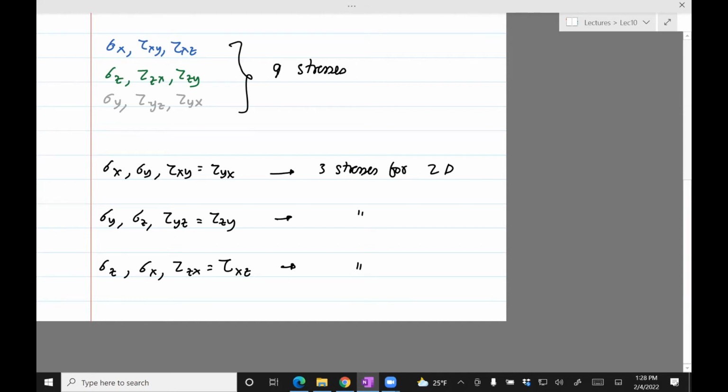So what we are looking at here as plane stress with sigma x, sigma y, tau xy, that's one case. Then we do it for the second case, sigma y, sigma z, tau zy. And then we can draw 3 more circles. You know what, let me just not call those 1, 2, 3, because I know it will be confusing. We had 1, 2, and 3. So we draw a Mohr circle for case 1, a Mohr circle for case 2, and a Mohr circle for case 3, right? You can do that because you have 3 numbers representing plane stress.